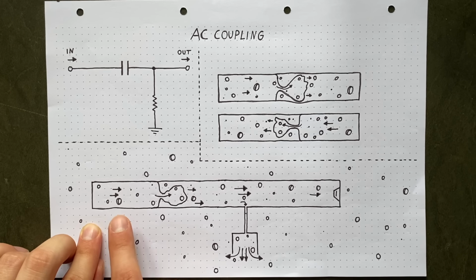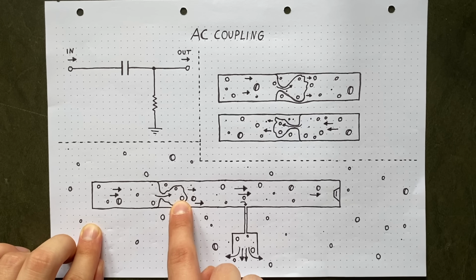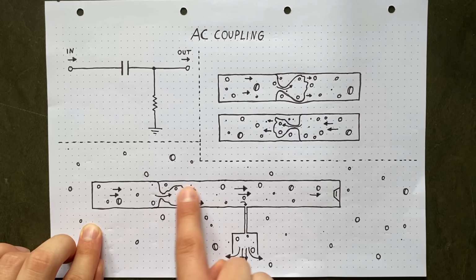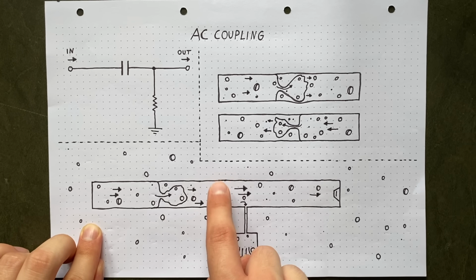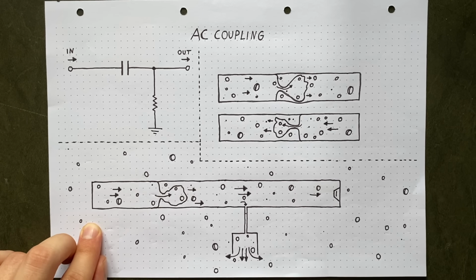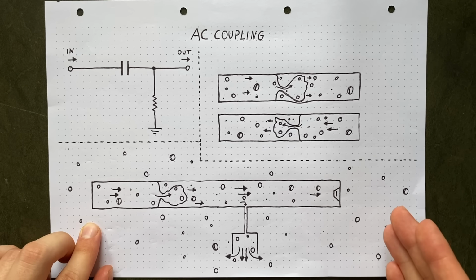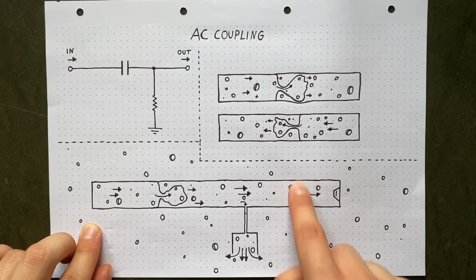Then, once we've completed the bottom half of our waveform, we go above 5 volts on this side, and our balloon will inflate and stretch out again, pushing the water here to the right. And the pressure will go positive, making the voltage rise above 0 volts. So we've recentered our oscillation around the 0 volts line.